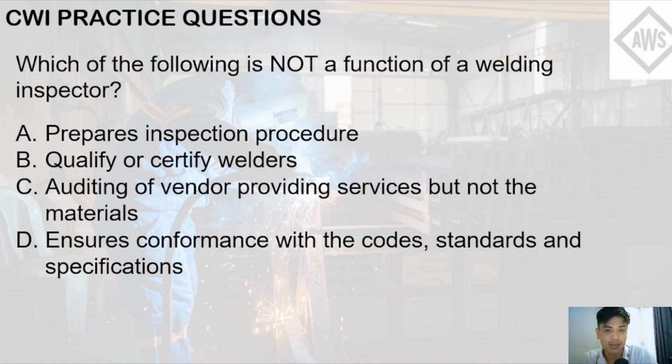The documents like MTRs, mill certificates, the factory standards that are used for the base metal, the production of the base metal, the testing or the destructive testing used prior to shipment should also be analyzed and scrutinized by the welding inspector.